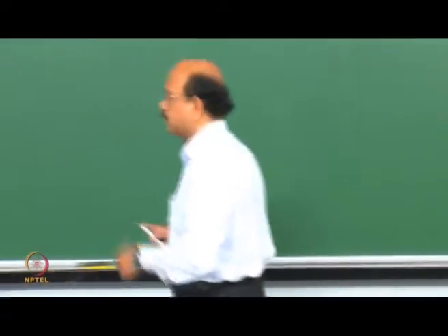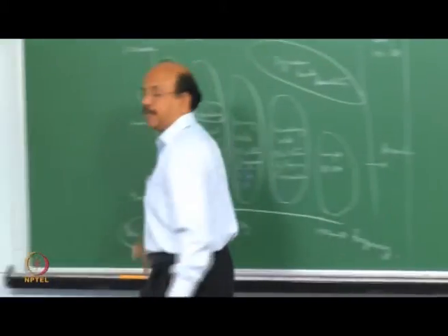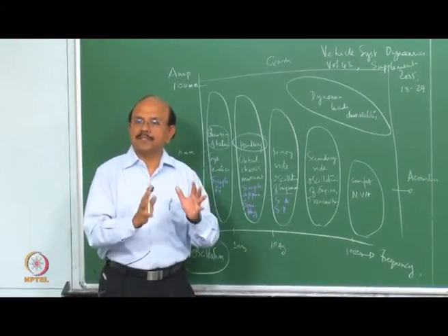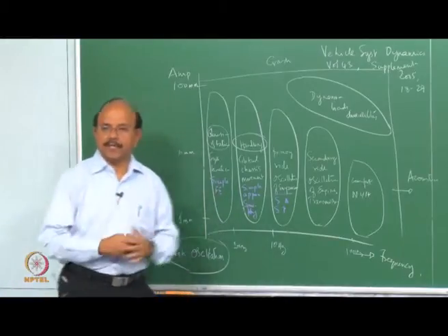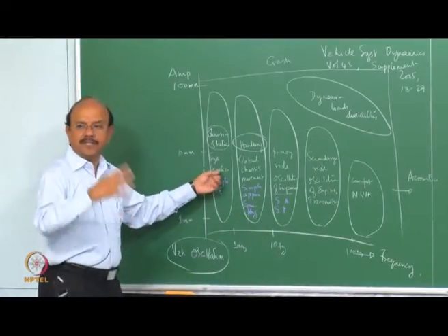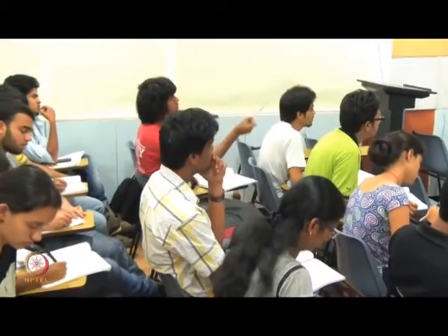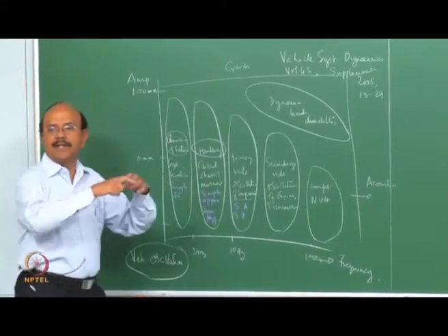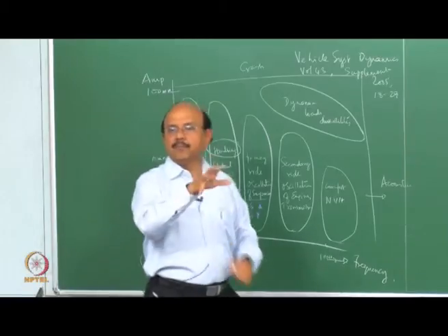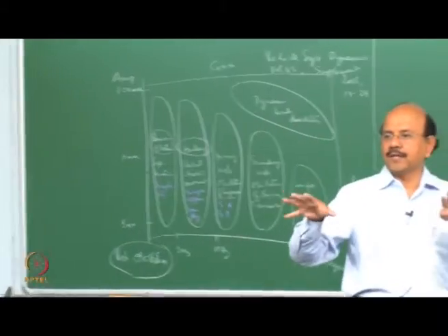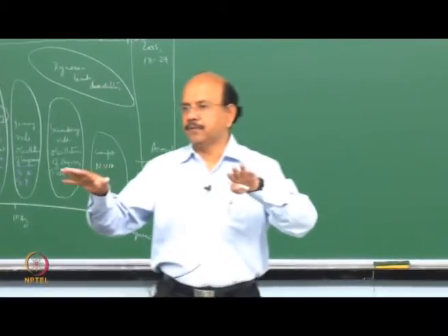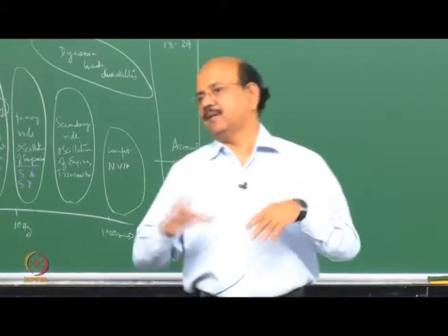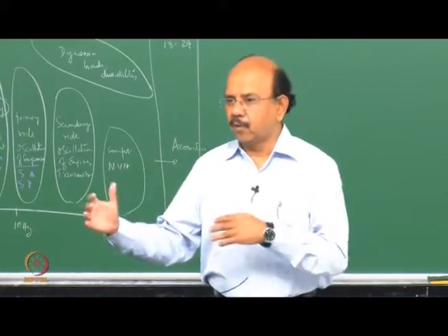What are the quasi-static oscillations you are interested in? Quasi-static is where I am looking at suspension mechanisms, steering mechanisms, so suspension kinematics, steering kinematics, and so on. These are when I give a steering input, what is the range to which the steering has an effect on the wheel, and whether Ackermann steering is completely followed or there may be error.